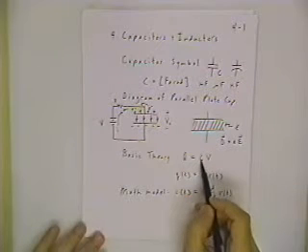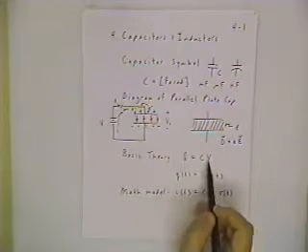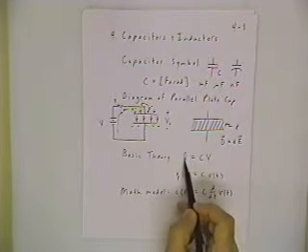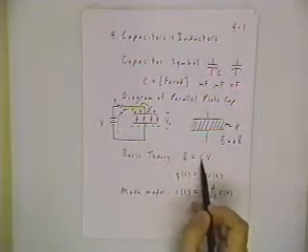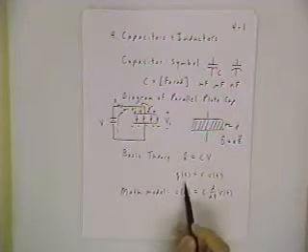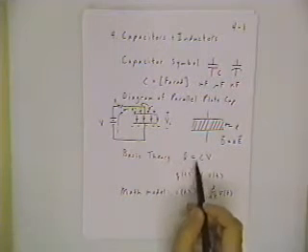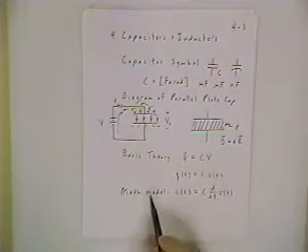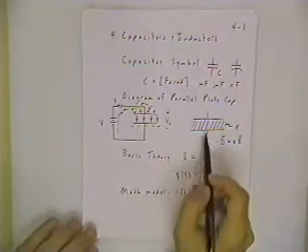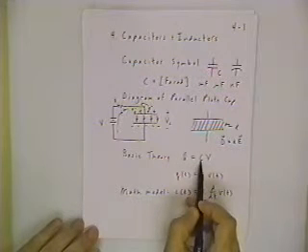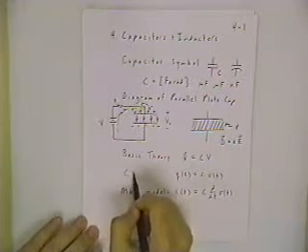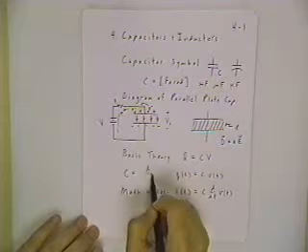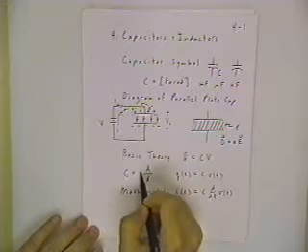In fact, our basic capacitor model is that the voltage across the capacitor is proportional to the charge stored by that capacitor, and in this equation the proportionality constant happens to be C multiplying times the voltage. I guess historically it could have been set up the other way, with V equal to some constant times Q, but this is just the way it happened to be invented to begin with. For this parallel plate capacitor, you've got a mathematical model for where that capacitance comes from. It's proportional to the cross-sectional area and inversely proportional to the separation.